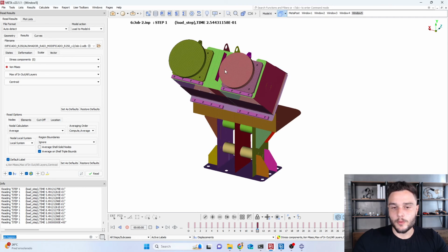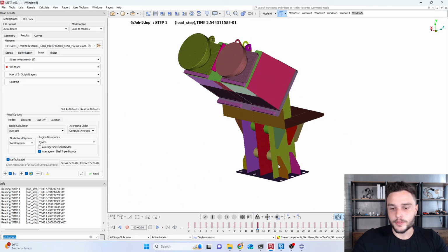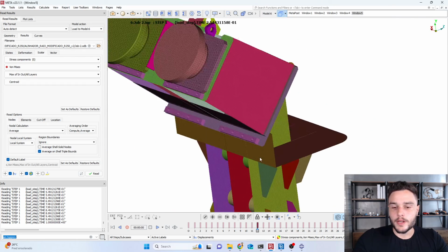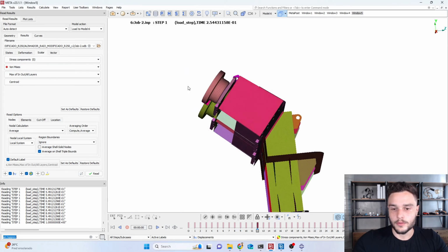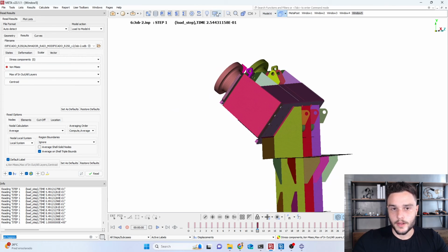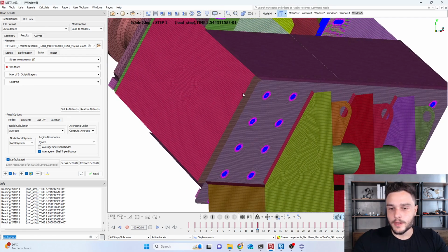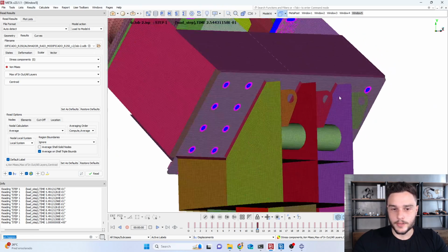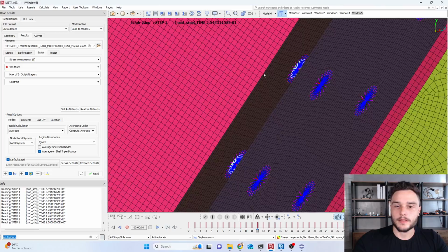And since we were not interested in analyzing the stress throughout the whole structure or anything like that, I could simplify the bolted connections that we have throughout the whole model. Let me show here the MPC and couplings. And you see that here we have many bolted connections, for example, between this plate and this other plate.